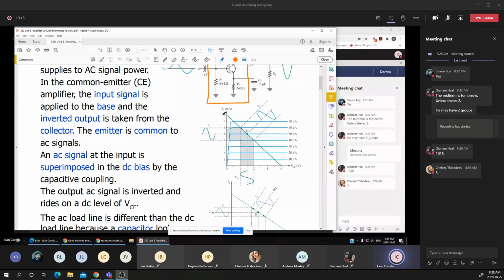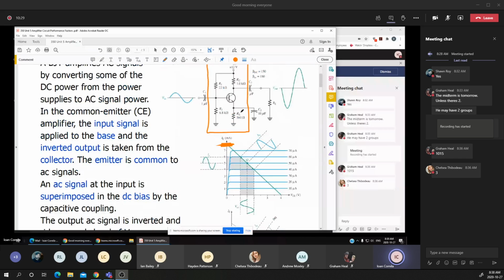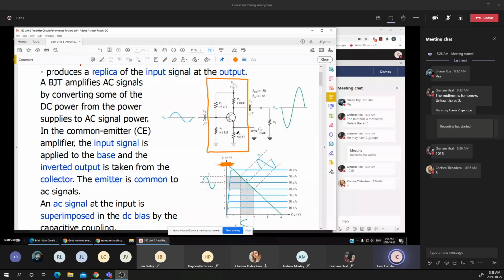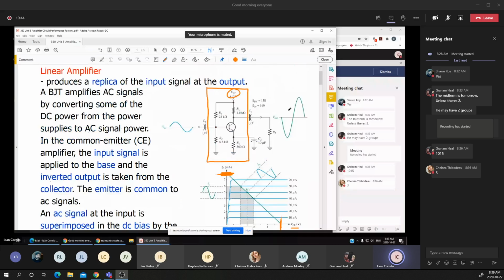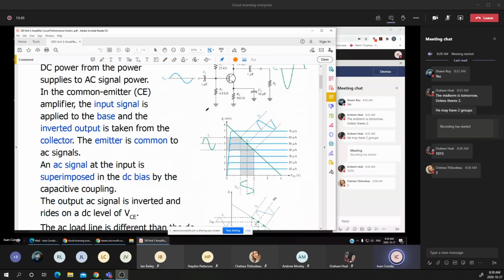It means that the largest current, the saturation current, that's the maximum current, is given by the supplied voltage, the RC, eventually the RE, as in this circuit. And the other extreme point is actually the supplied voltage, which is the VC max. The VC max is equal to the VCC, or the supplied voltage on the collector.